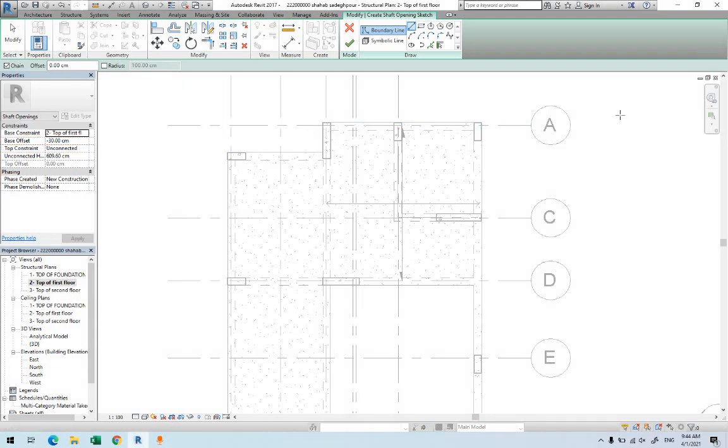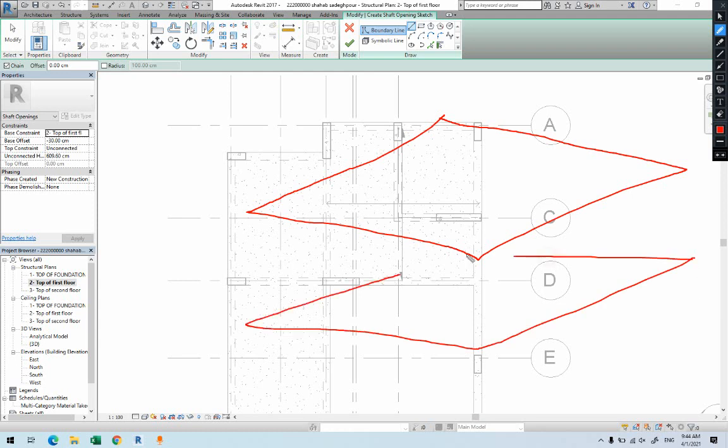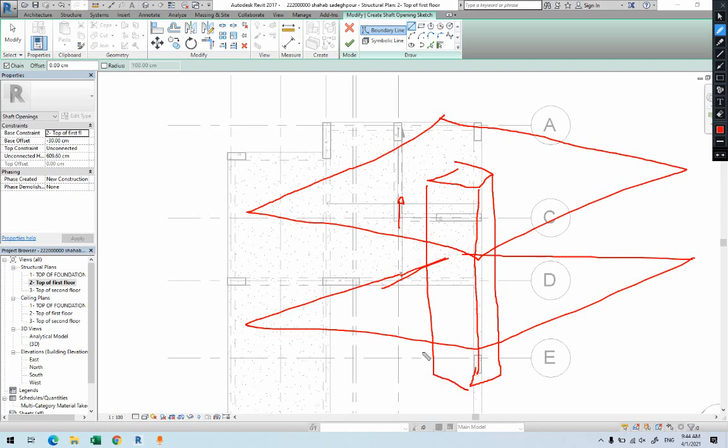Imagine this, if I go to 3D, just to show you something. Let's say we have this slab here, and we have another slab at the bottom of this one. We have another layer. When we create the shaft, it basically starts somewhere and punches through the slabs. So you will tell Revit to start somewhere above here and go below this one, because we want to cut both of these slabs. So we will start above this one with an offset and below this one with an offset.